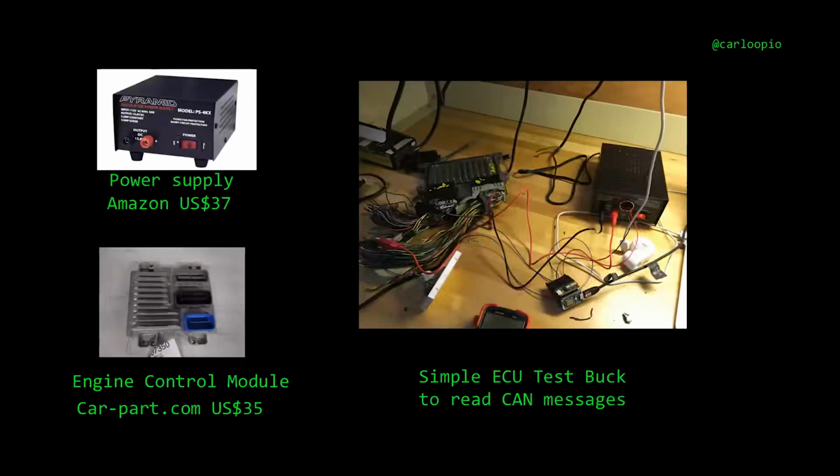Awesome. Let's see. We had someone ask, how do you access proprietary PIDs? Yeah. So PIDs, which are parameter IDs for OBD2, are harder to decode because they use a query and response structure. Those are specific to OBD2, so the data doesn't just stream. You actually have to send a specific PID to get it back. And the way I've seen most people do that is by using a scan tool.